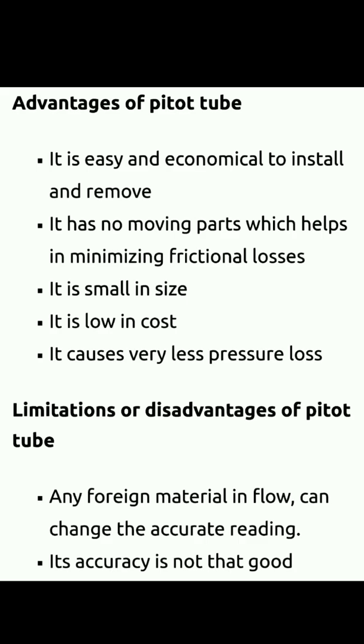It is low in cost because it does not have any kind of moving component and does not have any extra arrangement, so the cost is very low. It causes very little pressure loss. We do not have any moving equipment, we do not have any obstacle in the pipe, and we do not have a long length of pipe, so the pressure loss is very small.